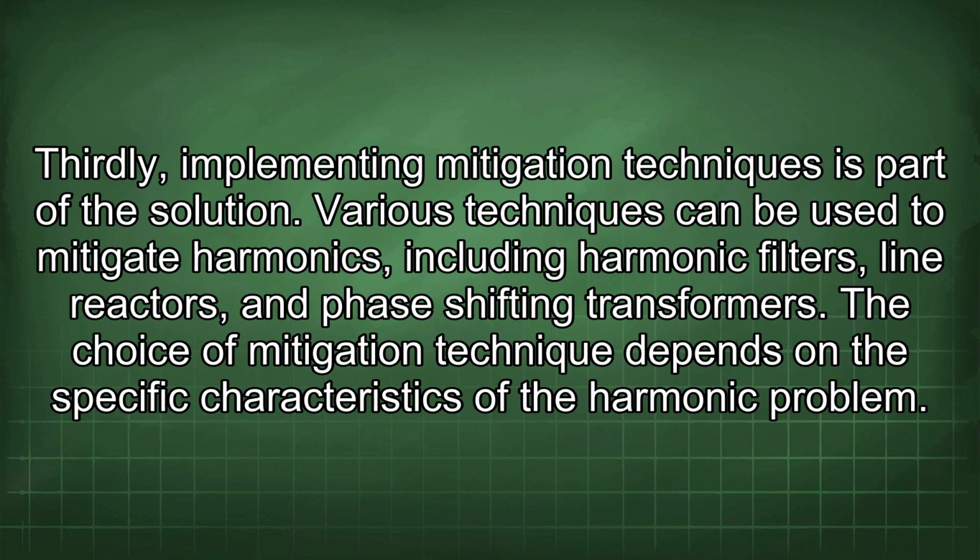Thirdly, implementing mitigation techniques is part of the solution. Various techniques can be used to mitigate harmonics, including harmonic filters, line reactors, and phase-shifting transformers. The choice of mitigation technique depends on the specific characteristics of the harmonic problem.